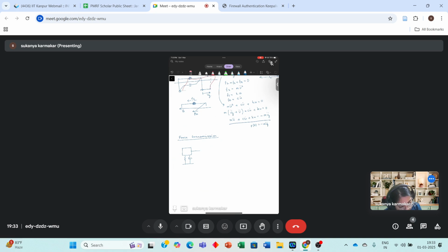And this is your variable x, mass m, and you are applying a force P naught sine of omega t. Because of this, you have to calculate how much force is transferred to the base. This is simply force transmissibility, and this is studied when you want to do vibration isolation.